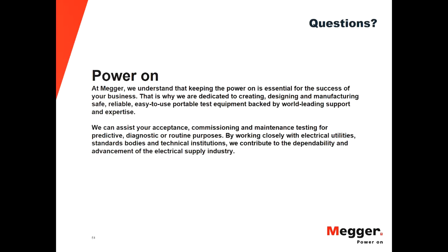So the test interval refers to the time between tests. And what we are referring to when we say 25%, we say 25% of service life. Service life is the life for which the battery is expected to be in operation, and that's provided by the manufacturer. Typically, it varies from model to model, but it's typically in the range of 10 to 20 years. So you can look at the manufacturer's specs and find out about the service life. Based on that, you can decide how often you want to run the test until you see the capacity degrading.